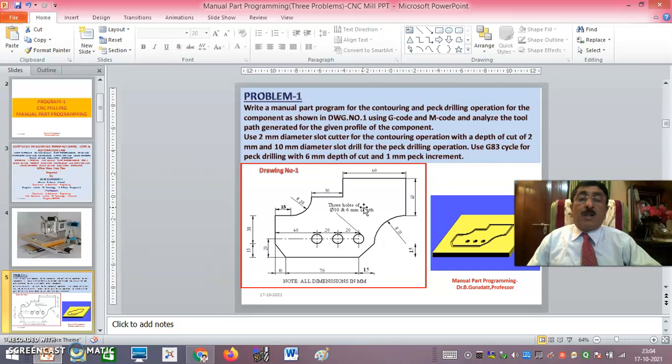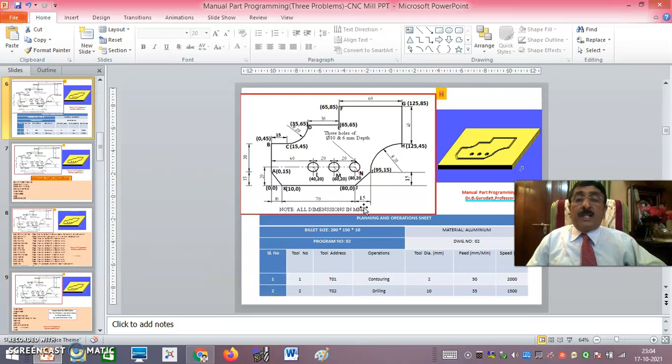The programming has already been written, as you can see here. First get the coordinates and all that. Any rapid movement is G00; I have used G and M codes. Linear movement is G01. This is BC, also G01. Going anti-clockwise is G03, or if it is clockwise it is G02. That way this is G01, G01. In that way I have written the program already, started from A, ended at A.